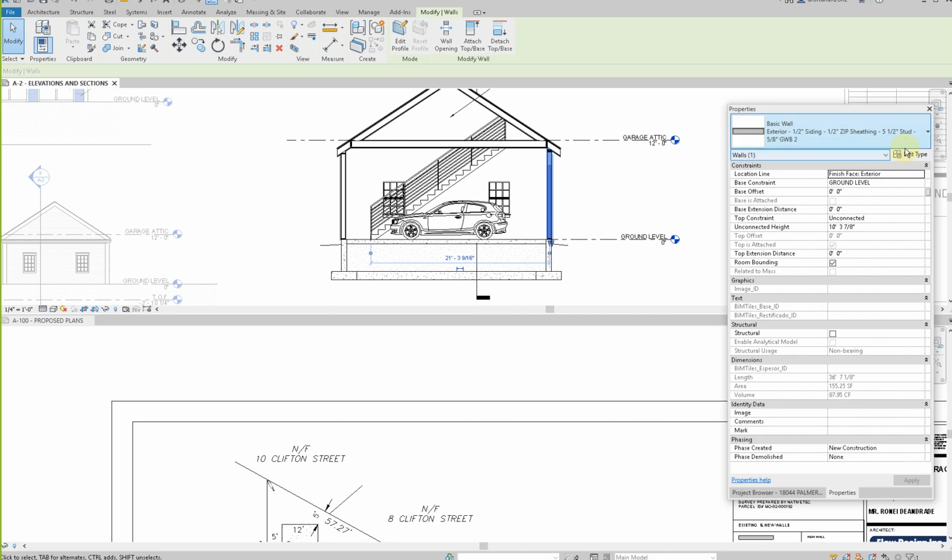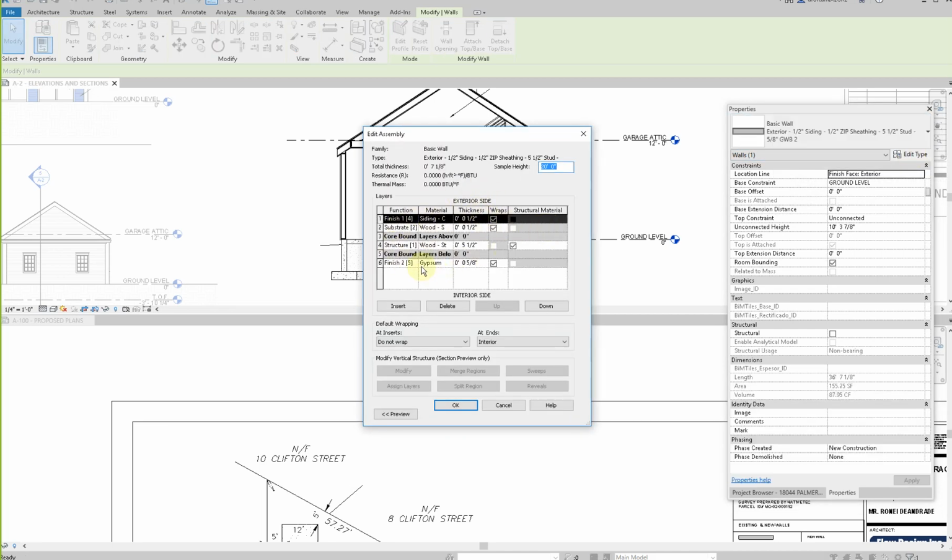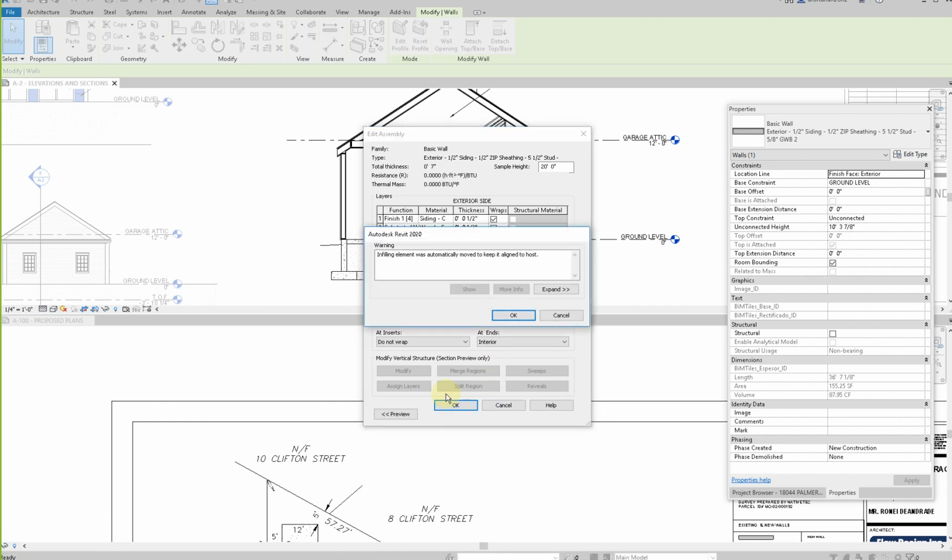Those are the layers of that wall. Okay, so I think that's okay. So we're gonna use that. In fact, the gypsum should not be 5/8. It should be half an inch, because for residential purposes we don't use 5/8. Well, I correct myself. If it is a fire rated condition or for a particular reason it needs to be strong, you will use 5/8.